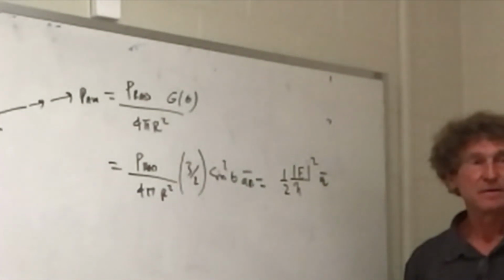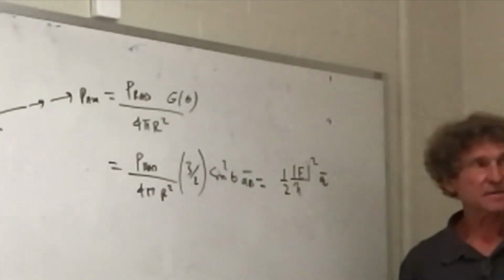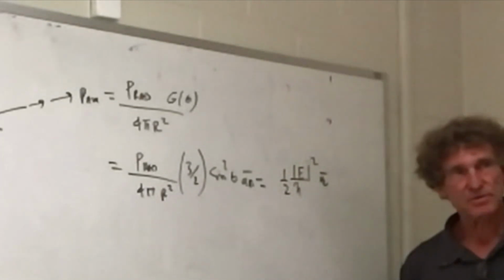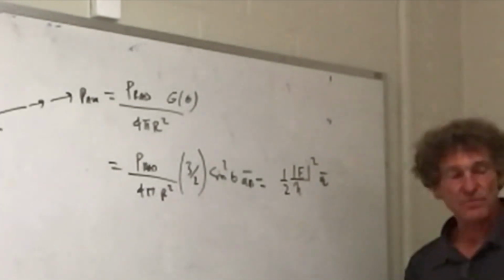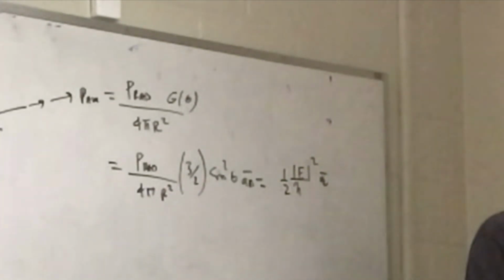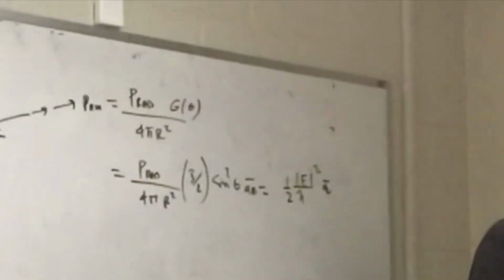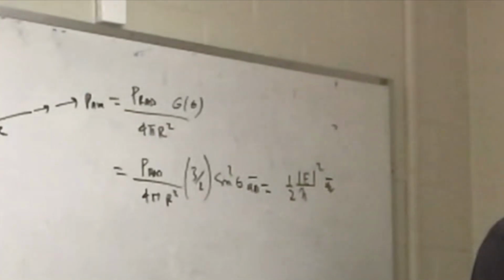So, I'm showing you how I think about these things, and it makes things a lot easier. I got the electric field really quick. How would I get the H field, just knowing it's a propagating wave? Anyone? Divide by eta, right, if it's in free space. Does everybody agree? Just trying to make sure I'm clear. You with me? All right, now that's a short dipole, and I've really uncovered everything.